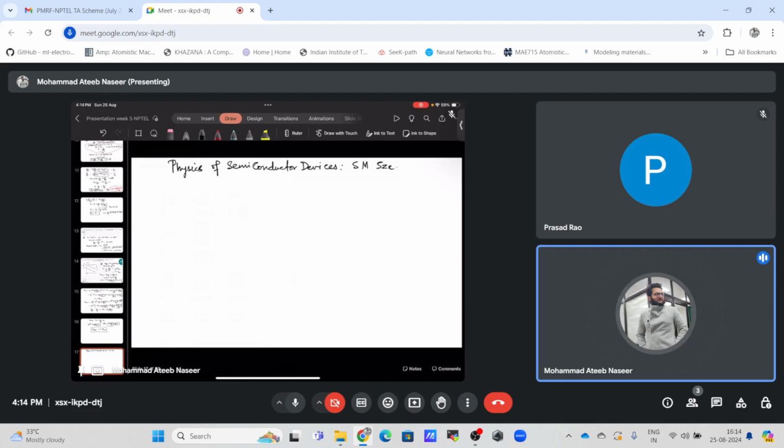Okay, so whenever, for example, a metal makes contact with the semiconductor, we will have Fermi level balancing, because whenever we are in thermal equilibrium, the Fermi level has to be constant throughout the whole system. If I am contacting the metal with the semiconductor, they will equilibrate in such a way that the whole system will have a common Fermi level at thermal equilibrium.